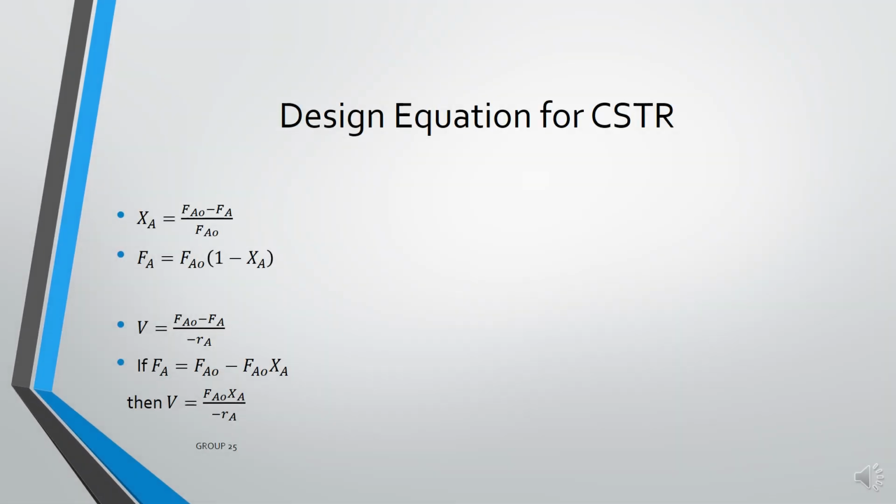The design equation for CSTR. After going through this process, the design equation can be written in terms of its volume as V equals FA0 times XA all over minus rA.